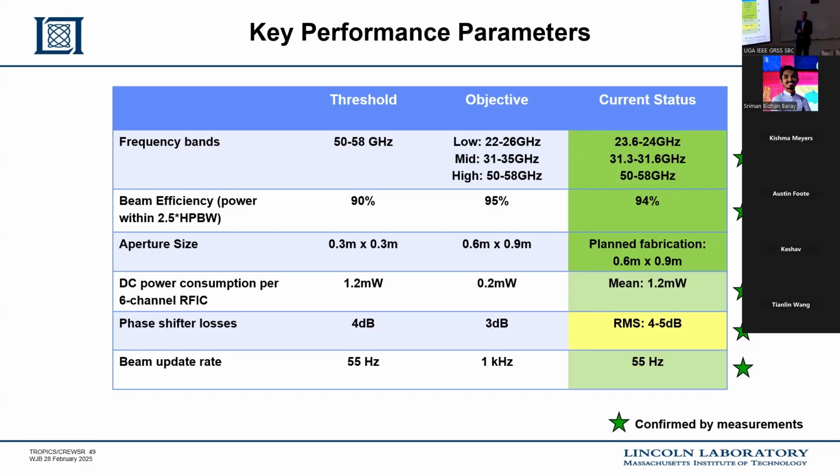I change that into a switch, which I can do with 1 milliwatt, not 30 milliwatts. And I get the power level down to about 50 watts, not 3 kilowatts. Now, the penalty that I pay for that is here. The phase shifters are lossy. So I've got to deal with that loss in the panel, and that hurts me in two ways. The sensitivity of my measurement is not as good, and I have to calibrate out the effect of the panel.